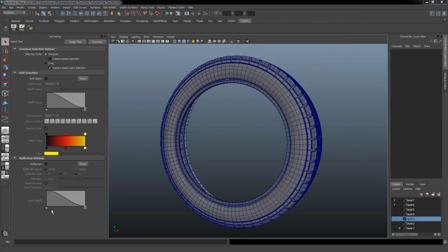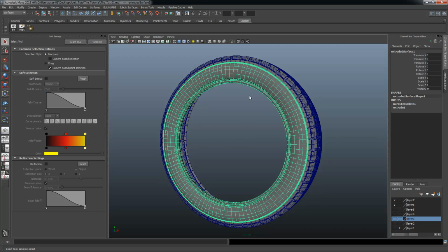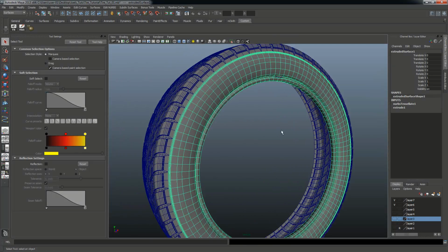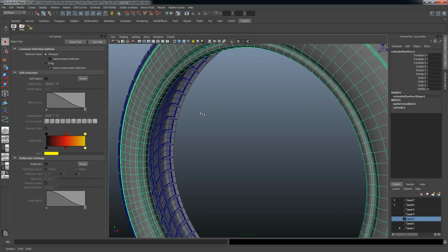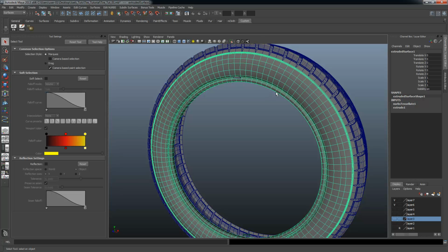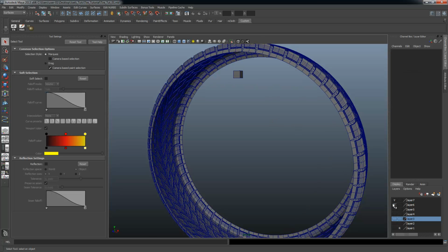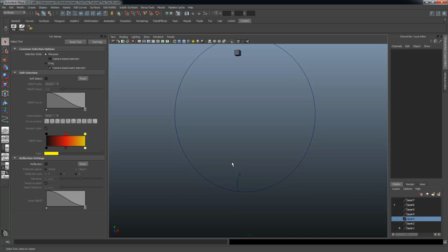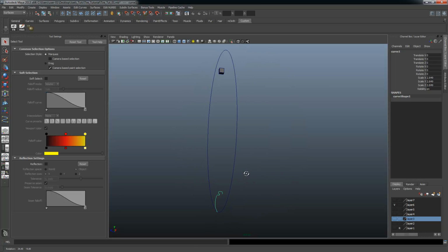Hold on one second, I'm going to figure it out and I'll come back. Okay, so Maya can be a little finicky at times, and it can really come down to something as stupid as it just didn't like the direction that I was drawing my curve, which is how it turned out to be the case. I just started trying different things because I thought my settings should have worked. I've had those settings before and had no problem with them. And so what I did was I drew my curve here, instead of from the top down, from the bottom up, and that solved all my problems.